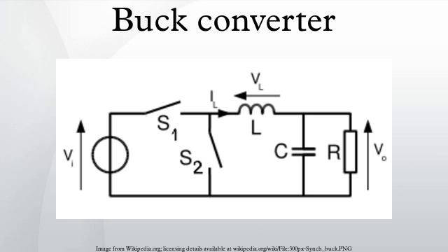This yields the value of I. The output current delivered to the load is constant, as we consider that the output capacitor is large enough to maintain a constant voltage across its terminals during a commutation cycle. This implies that the current flowing through the capacitor has a zero average value. Therefore, we have the following, where IL is the average value of the inductor current.